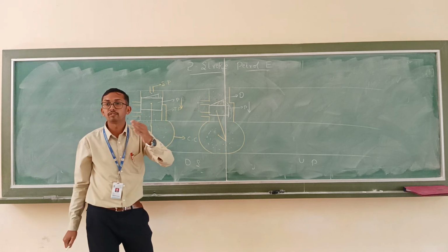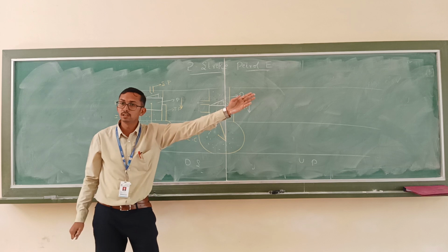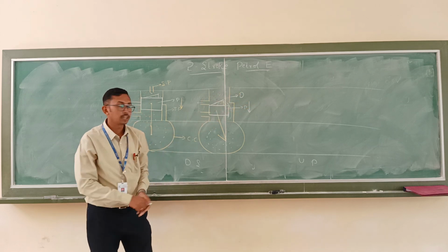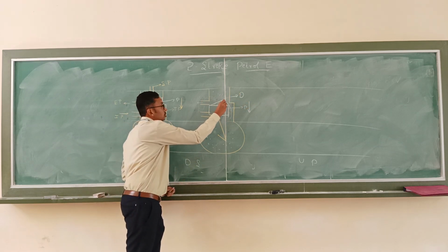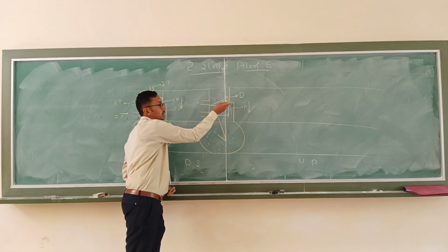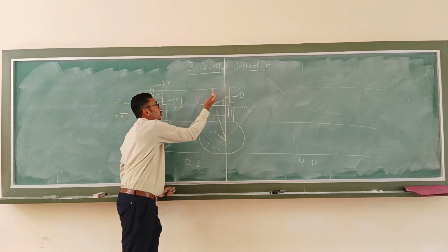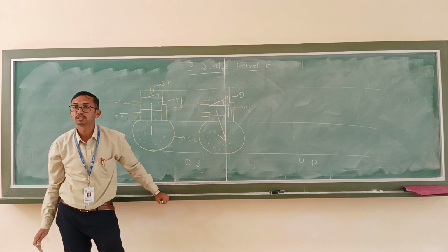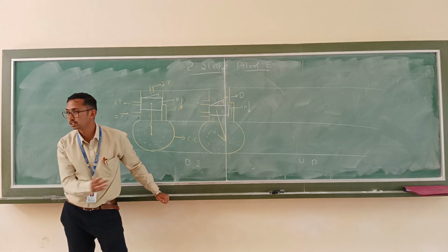That means the fresh air fuel mixture itself is going outside the cylinder. That's why, with the deflector there, it is going to move upwards and push out the waste gases outside the cylinder to the atmosphere.